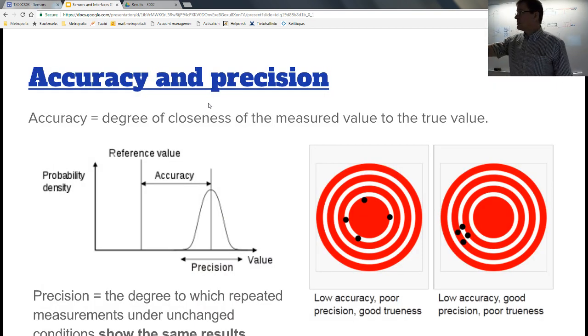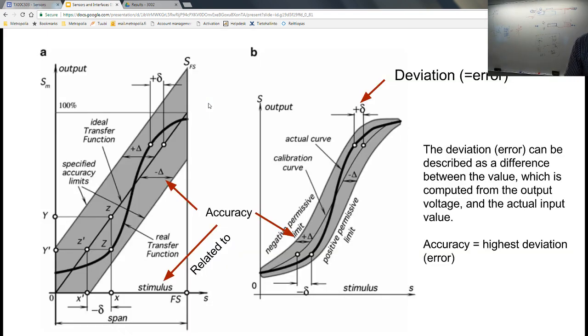Okay, one more thing about this. So how to actually improve the systems. If it's accurate but not precise, then you can start doing statistical methods to actually get a better accuracy. On precision, you basically need to do calibration.